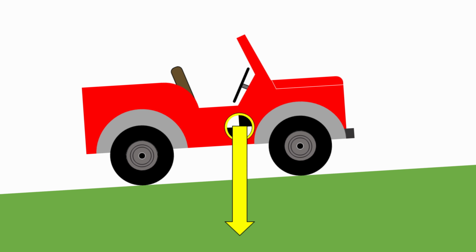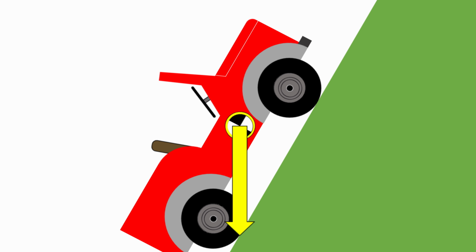Longitudinal stability is also important. So longitudinal stability tends to be less of an issue. We tend to see fewer vehicles that fall over longitudinally. The vehicles we do see fall over longitudinally tend to be things like ATVs that have a very short wheelbase and quite a high centre of gravity, because obviously a lot of the mass of an ATV is in the body of the rider. So it's not unusual to see ATVs either pull a terminal wheelie or even fall over forwards sometimes.